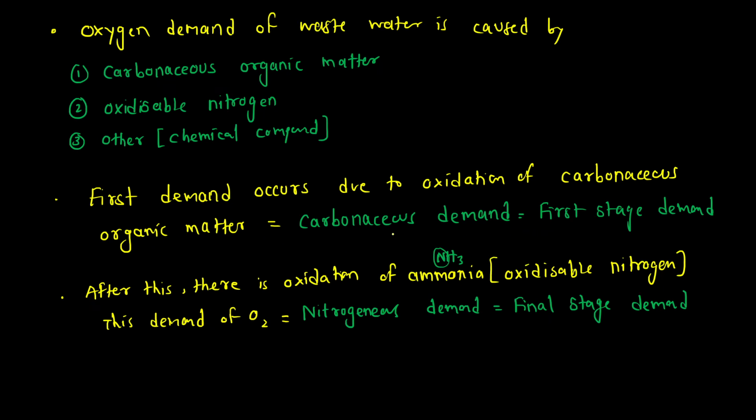Now you should write one point here, that this first stage demand, that is oxidation of the carbonaceous organic matter, is completed in the first 5 days. Okay, so in the first 5 days only it is completed, and the oxidation of nitrogenous demand starts after 5 days.